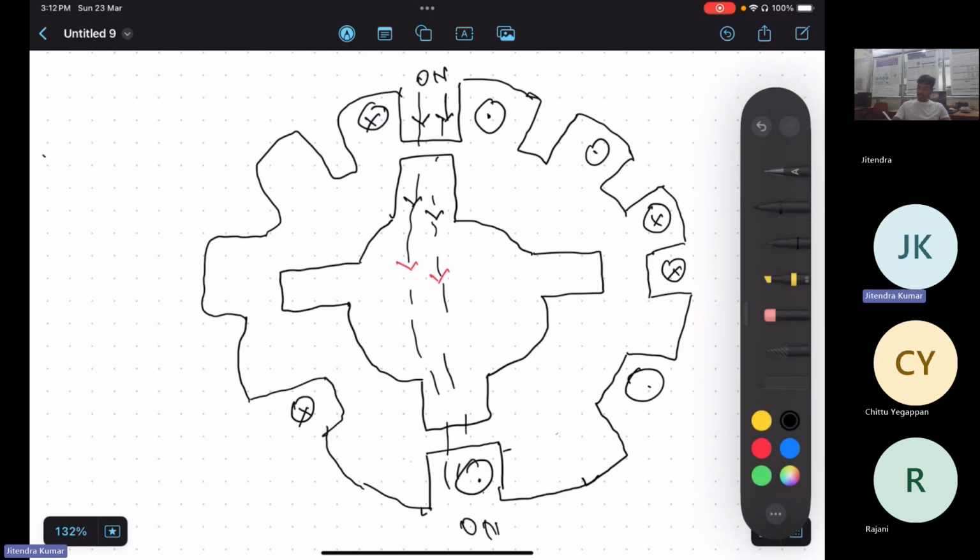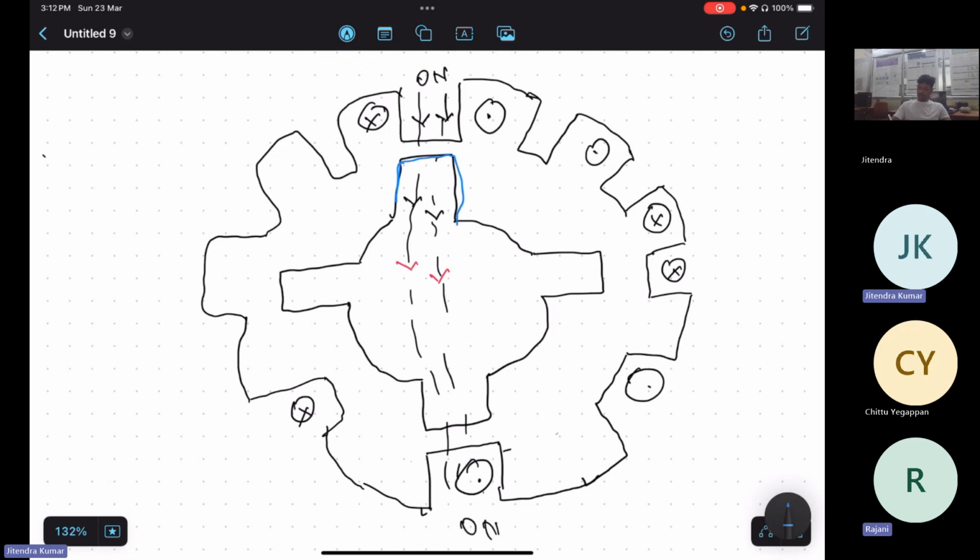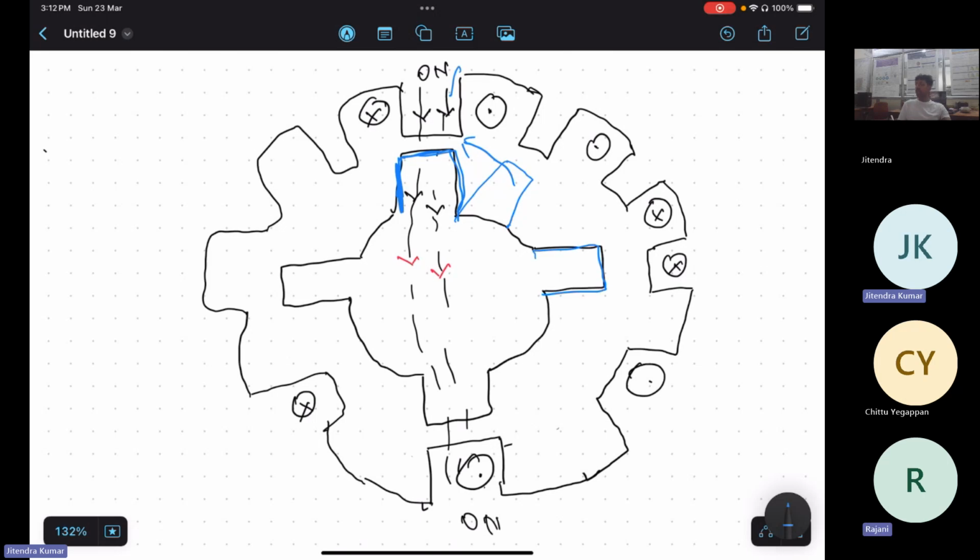And if this rotor is slightly unaligned, let's suppose this rotor tooth is here. When this supply is on, it will provide flux, and by the force, this pole should attract. With this attractive force, this rotor tooth will align at this position. Now the next rotor tooth will again be at a partially unaligned position, and now you give supply here.